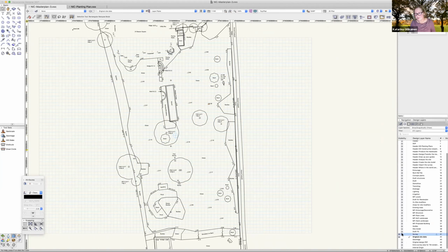Here I have set up how I want my first site model to work. We have the maximum elevation, we have a minimum, which I'm going to put down to 0. I want to have the contours at 200, for example, and every 5th will be a major contour. For the 2D display, at the moment we're going to look at the existing only, and I will have the flow arrows on for now.